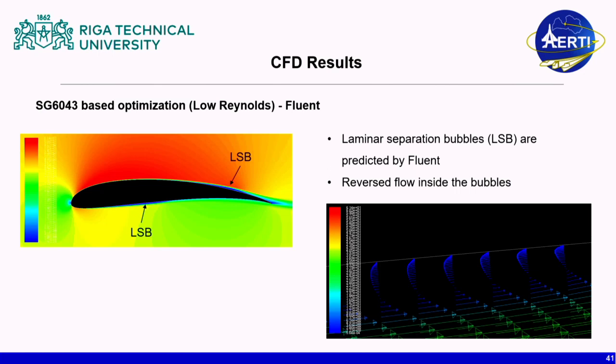So here, in this slide, the flow mechanism over the aerofoil is presented. The formation of laminar separation bubble is observed exactly at the upper surface as well as the lower surface of the aerofoil. These surfaces of the aerofoil produce this bubble, and this bubble is in fact the reason for the increased drag that we saw in our computational results.